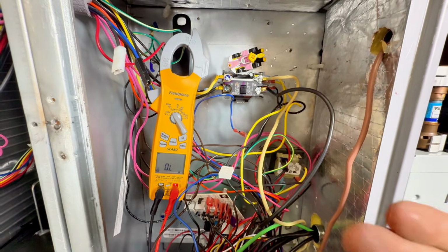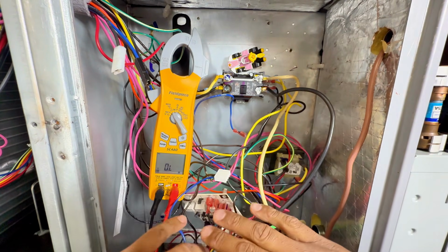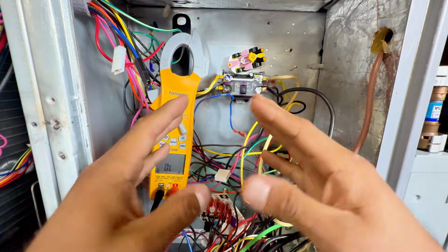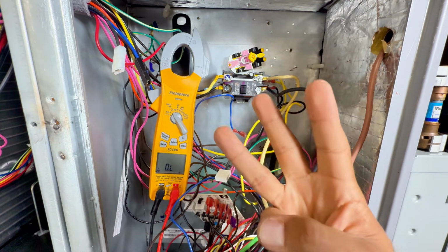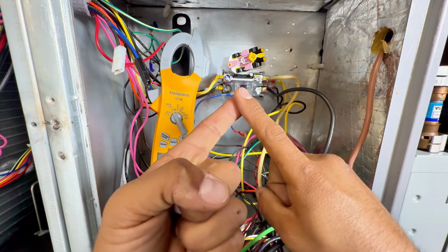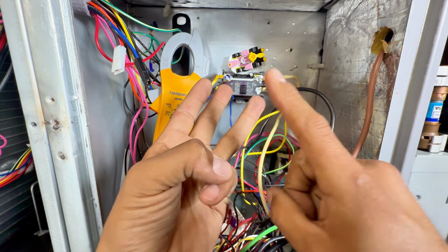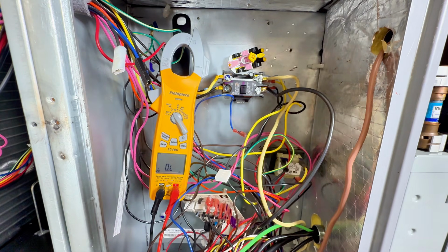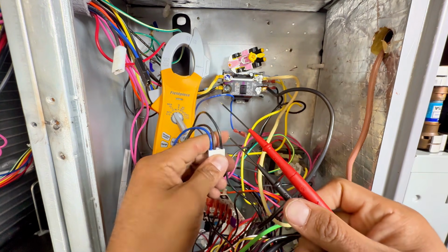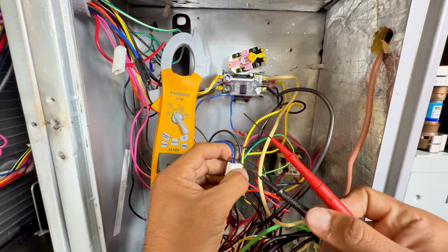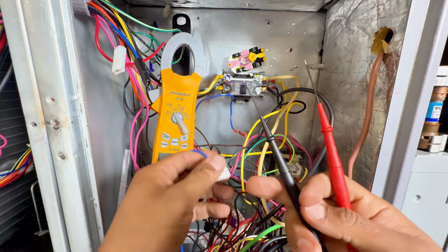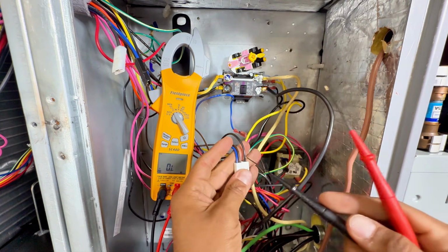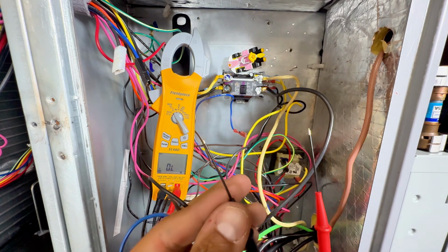Okay, so this is more on the troubleshooting side, but let's say everything is wired right. You figured out how schematics work, but this contactor coil can be bad. Remember, there's three things to a circuit. You need a load, you need current, and you need potential difference, or your voltage. So the way I like to do it, you see this plug here that we were talking about earlier. This blue wire, my 24 volts, goes to the 24 volts that powers up the contactor coil. So you put it on continuity, and then you have to use the little leads, right?